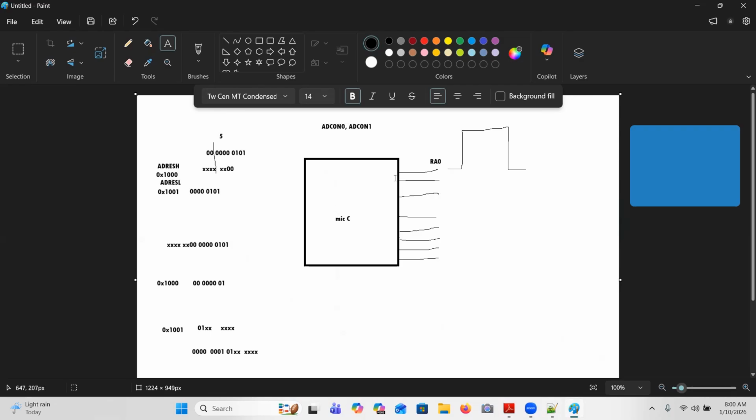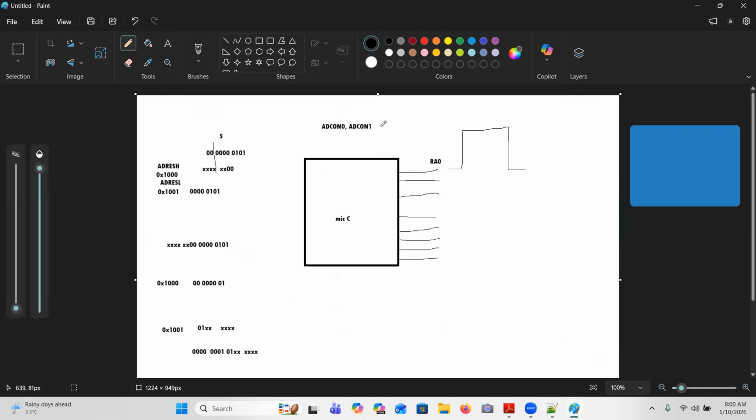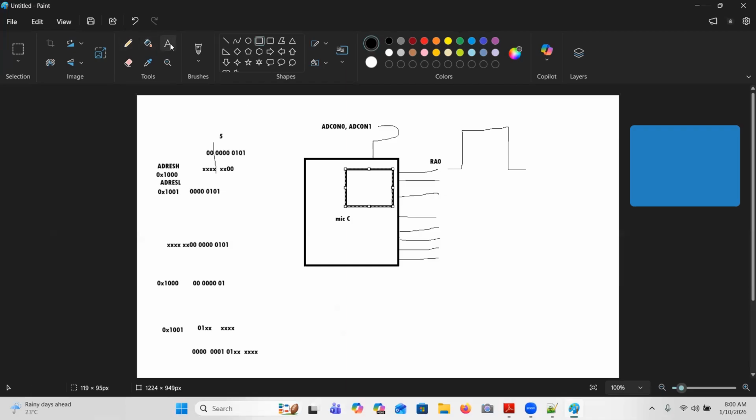Your 5-volt result, the digital word that you get after the ADC conversion, will come and sit there, not here. These are just control registers for how this ADC should operate. This is directly given to the ADC that we have inside this particular microcontroller. Understood? Yes, sir. Understood.